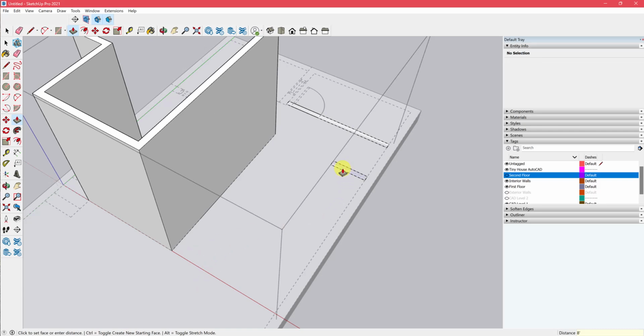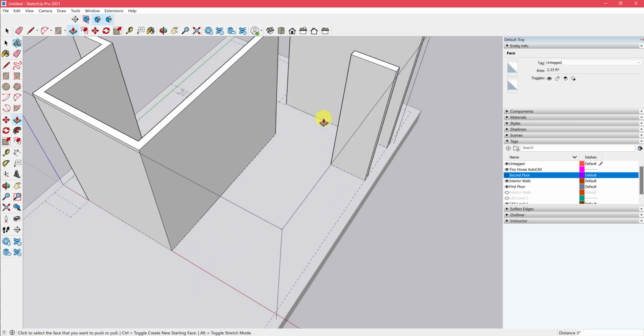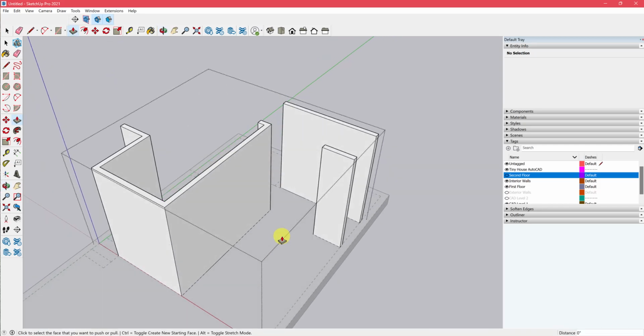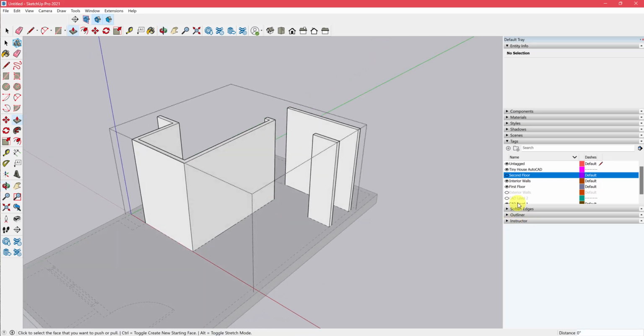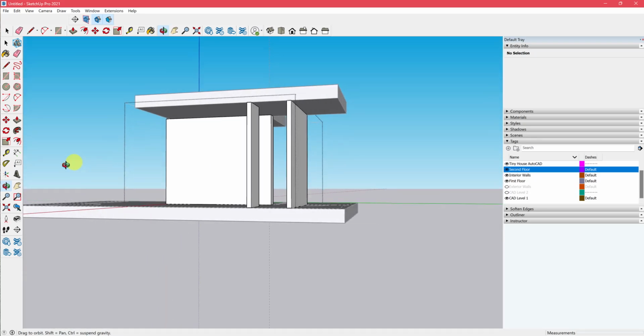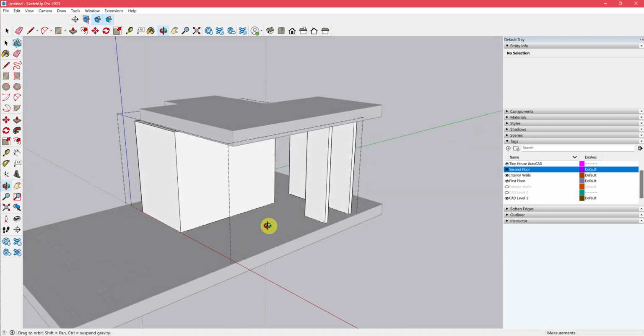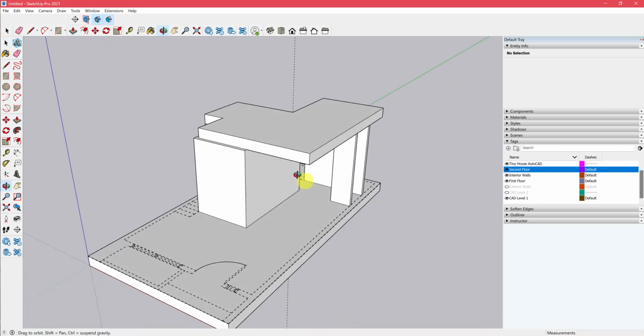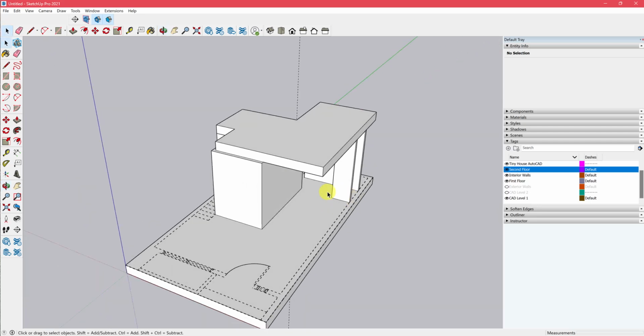And I believe we learned last week, if we just double click those other surfaces, SketchUp basically redoes the same command. So since we just extruded this 8 feet up, if we just double click those other ones, they'll also match that 8 feet. And then just to double check here, I'm going to turn on my second floor again to make sure, yep, those did get at the right height, just to the underside of that second floor. Click away from my interior walls group. Let's see here, did I miss anything? Nope. Awesome, so we're on step number 6.